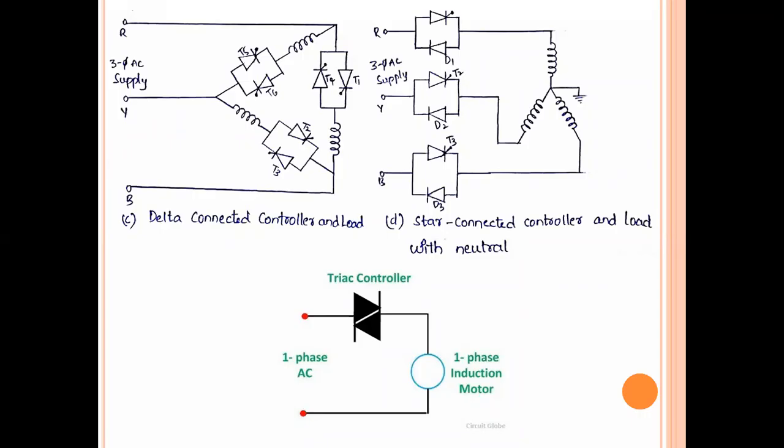And because of this third order harmonic, generally this harmonic increases the losses and thermal loading in the motor. The losses are increasing means losses will obviously produce heat in the motor, right? So that means the heat of the motor increases, which increases the thermal loading. Simply we can say, technically, thermal loading of the motor is increased due to the losses. So third order harmonic is very much effective in the reduction of efficiency.